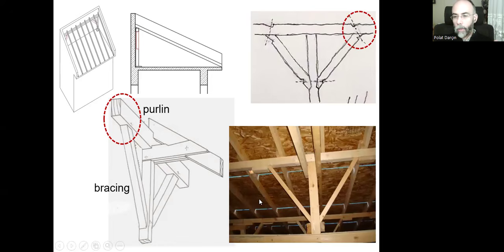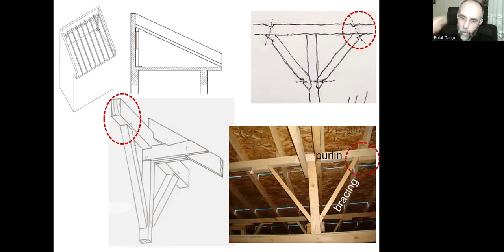Or instead of carving out all these pieces and trying to connect them with bolts, we can prefer a simpler way of connecting these pieces. I think you remember this example from last week's course. Here we see an intermediate purlin, and right underneath there's the stud, and on two sides there are two bracings. Here you can see they use little pieces of timber to support the ends of the bracing. It's just nailed without using complicated systems like bolts or drilling holes.